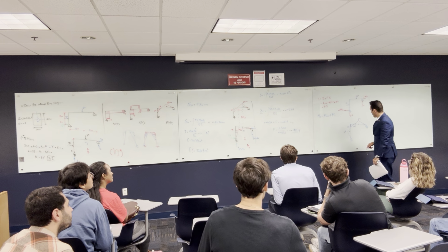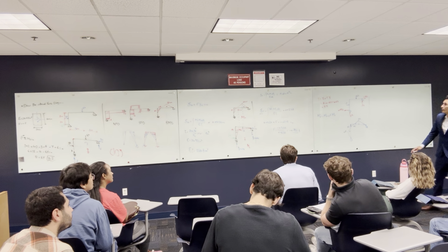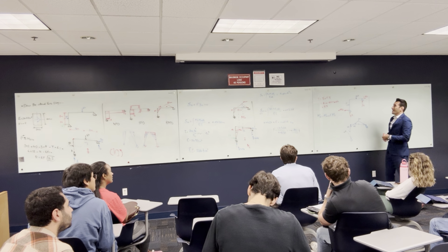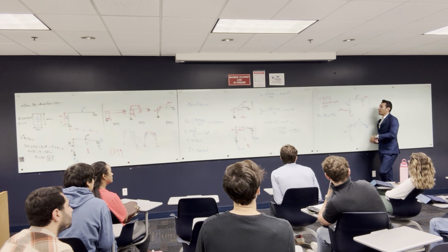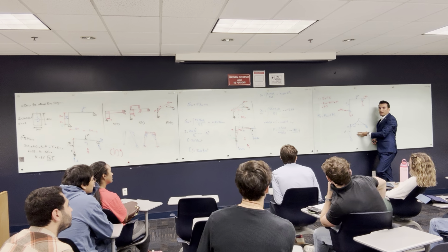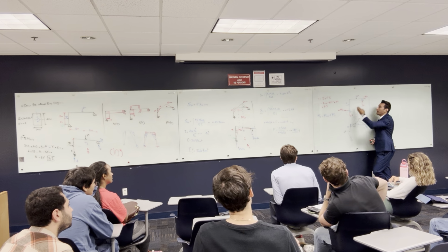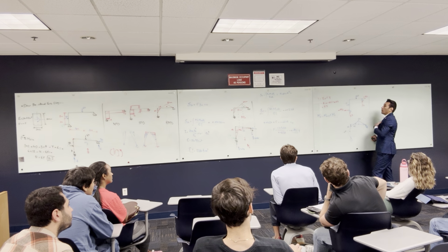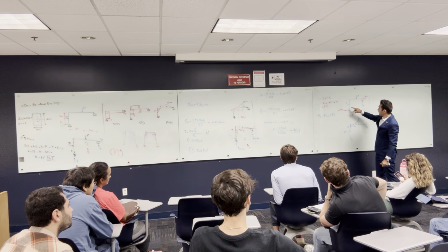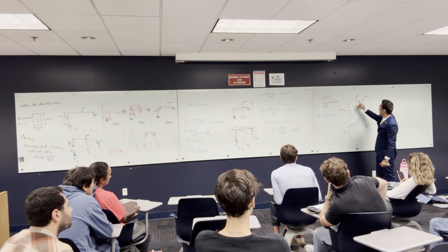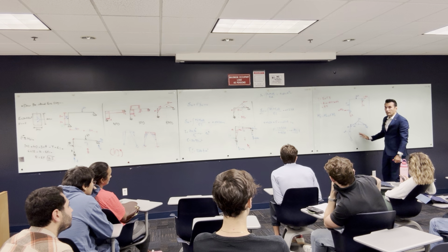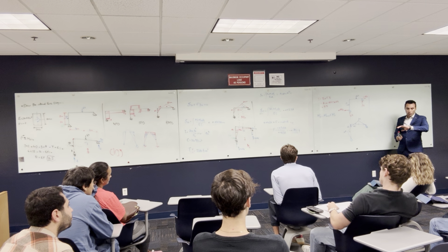All right. You can do the same thing to get the normal force diagram. But to be honest, it's much easier for me, if I have the reactions here and everything here, to use this to calculate the bending moment. Just find the new reactions and then get them section by section. All I need is the value of the moment here, here, and here. These two are 0, so basically I need 3 points, and I connect between them. Like this. That's how I draw the bending moment diagram.